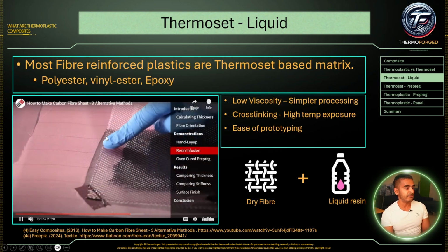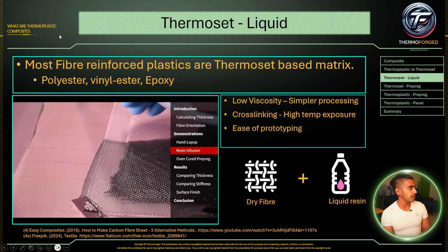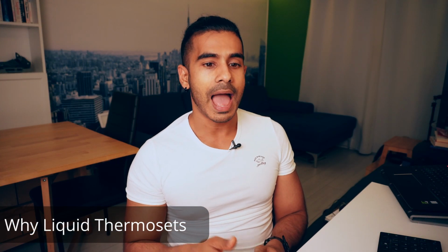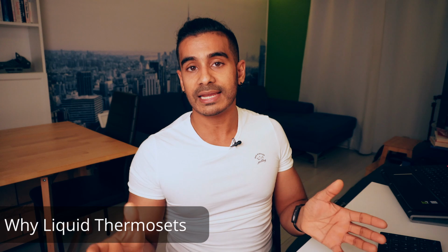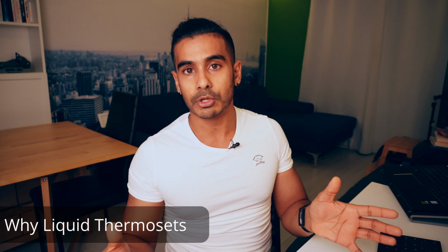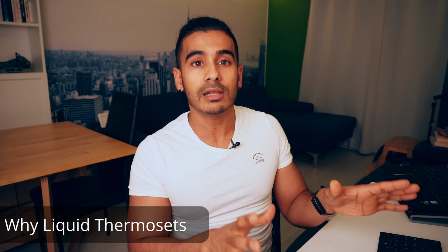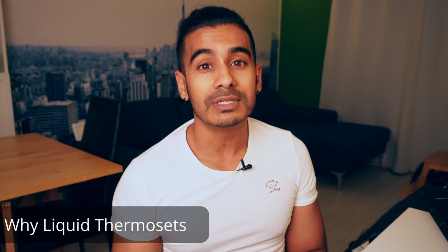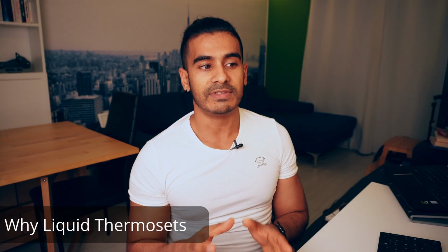So what's interesting about this is, generally speaking, you can have very complex geometry, you can have low cost tooling, and you will impregnate whatever complex geometry that you have. You wait for the material to gel and solidify, and then you can open up the bagging material, and then you can cure it afterwards in an oven. Generally speaking, the curing time on this is 6 to 12 hours. It can take a long time, but this is great for prototyping.